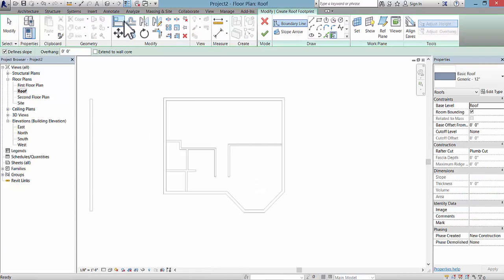So I'm going to click on roof, and then I have a roof that slopes. Sometimes it's better to create separate roofs and then join them. That's what I'm going to show you, because you may find that it will work out if you have an addition here and you have all of your sloped sides defined as we did in the first video. But this way, I'm going to show you a different way so that we can create them as separate roofs.